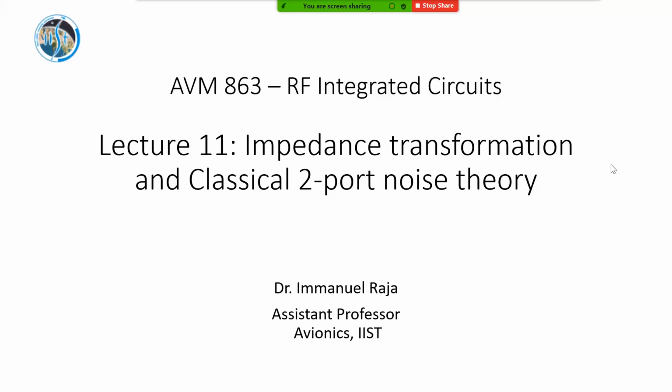Okay. Now something similar happens in many contexts, and impedance transformation is a very integral part of RF design in general and in RFIC as well, right? So in last class we looked at what was called the L match, right? And L match was like you can do an upward transformation